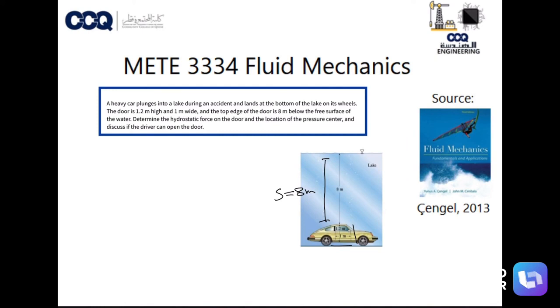For the driver, it is best to let some water in by rolling the window down a little, for example, and to keep his or her head close to the ceiling. So the driver should be able to open the door shortly before the car is filled with the water. Why? Since at that point the pressures on both sides of the door are nearly the same, and opening the door in water is almost as easy as opening it in air.